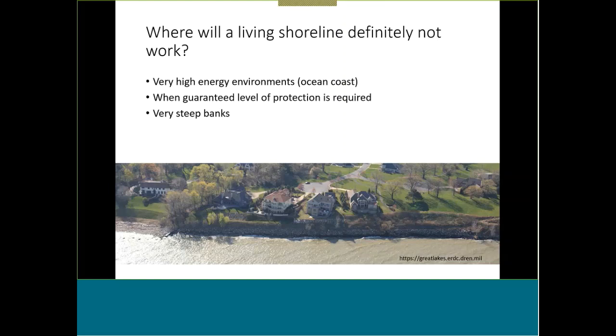Another important challenge to consider, and this is probably going to be one of the most often faced challenges with living shorelines, is very steep banks. In order to dissipate wave energy over a wide area, you oftentimes need to regrade the shoreline and the upland bank area. Looking at this picture from Lake Erie, you can see we have enormous houses very close to a very steep bank. There's just not enough room to regrade this to dissipate energy over a wide area. And so that's why you see a lot of stone being used for shoreline protection in this area. A living shoreline is probably not going to be possible in this case.